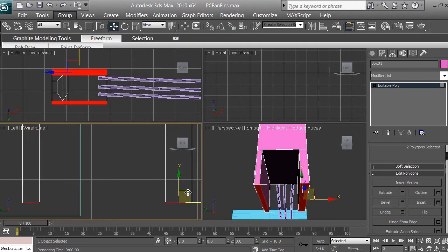See where your X and Y axis are right here, and it's kind of not comfy for you to have them right there. How to fix this? This icon right here, use pivot point center, click on it, hold it, and select this guy right here on the bottom, which says use transform coordinate center. Basically, whatever viewport you're on, it will bring the X and Y or Z axis for you right in the center, and it's very convenient for you now to move. So it's not on the left or on the right. This is another tip for you.